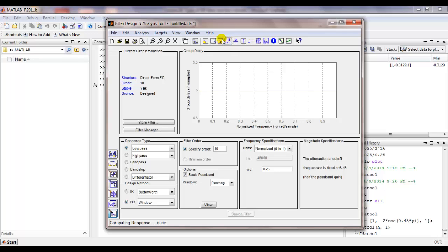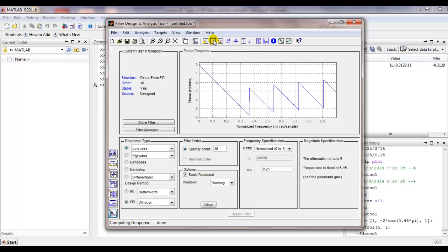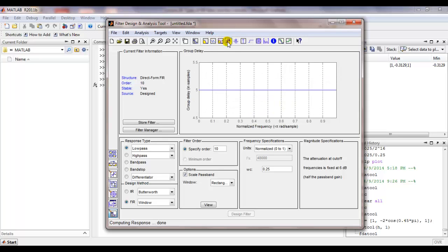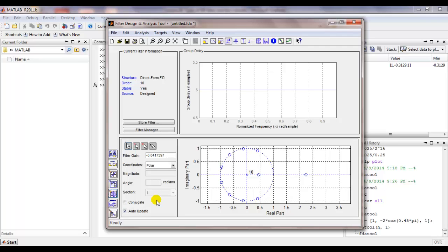And it's a constant, as you can see. And I could have looked at the phase response too. It's just wrapping. It is linear phase. The reason you see this going up and back and forth is because of the wrapping that goes on. So a group delay is a much better thing to look at than the phase. Okay, this is the case where you have a constant group delay. It's a linear phase filter. You are all good.